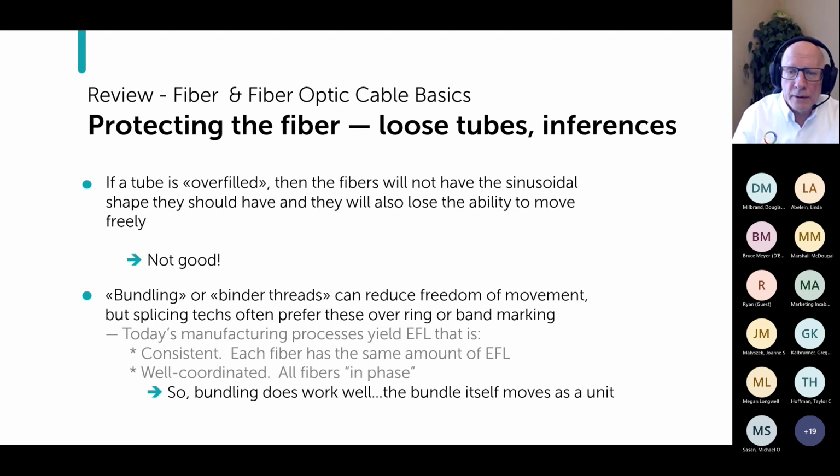There are 12 standard colors, but in OPGW, we're going to see later that you often have more than 12. So what do you do? Well, initially, 25, 30 years ago, we'll just try to add more colors. But that ran into a practical problem in the field, and that practical problem was that human beings were having a hard time distinguishing more than about 12 fibers under field conditions. So they dropped back to 12 standard colors, and then if there's more than that, you have one of two techniques that are used.